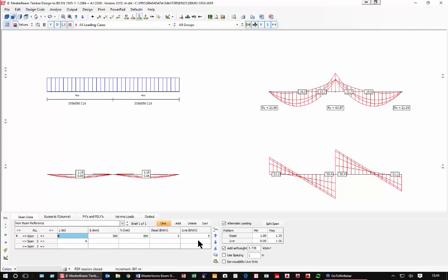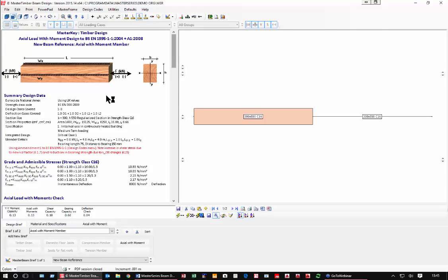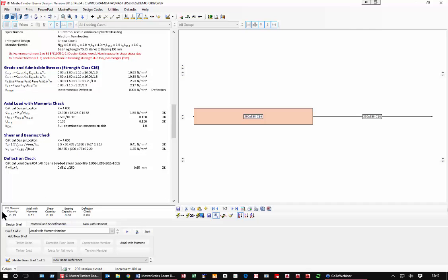And some nice deflections, and I'm not going to go for any more other than the section is going to be, and it's a pretty big section, it's putting it in as a timber section. I don't know what I need, so I'll just leave that as it is at the moment. We're carrying 1 meter wide of this loading, so we shouldn't need anything as big as that. So into design, timber design, and we'll see that I'm absolutely correct. Our designs are well under.